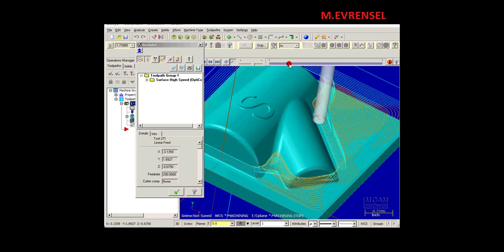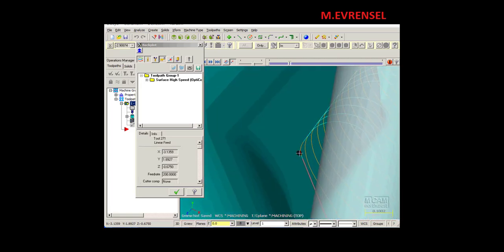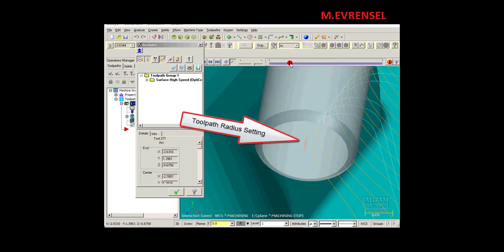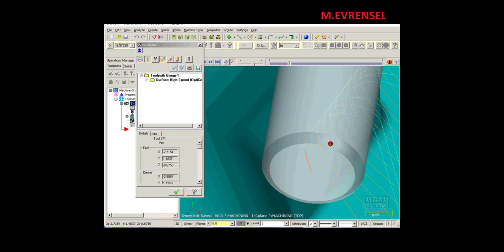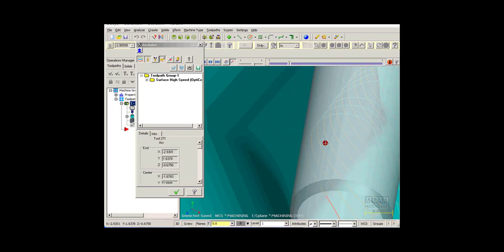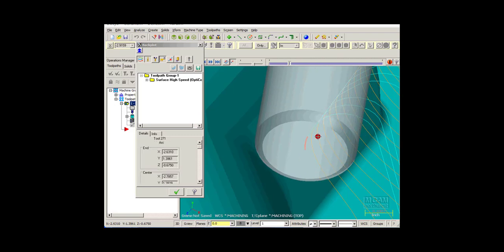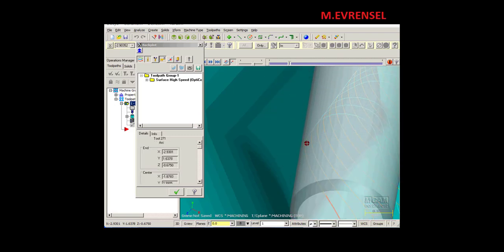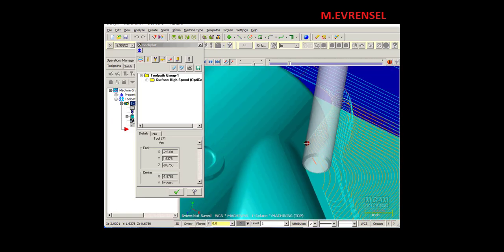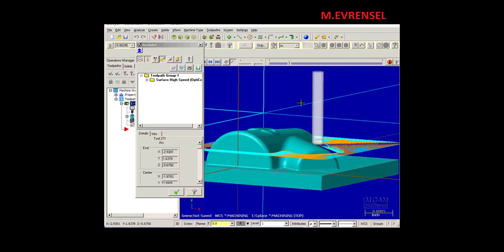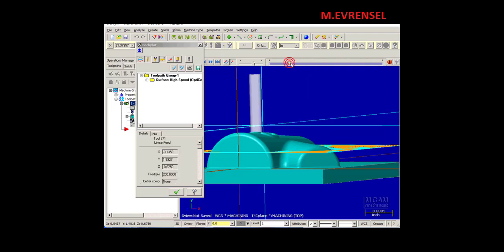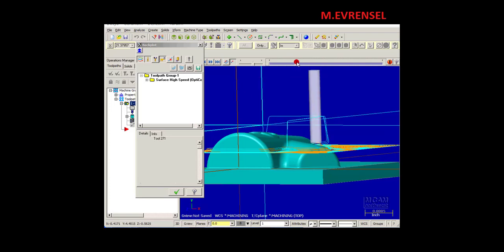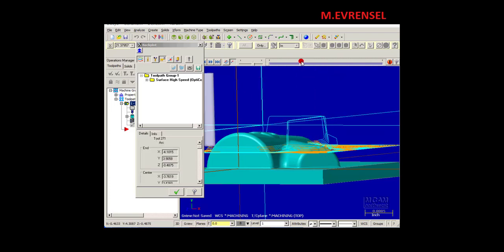Now you'll notice the detail. When the tool comes into a corner here, it's actually cutting a radius. It never will go into the corner and use the tool to form the radius, which would no doubt break at this feed rate and this depth cut. So that's the rounding radius we're seeing right there. Probably the most important feature in these high-speed toolpaths. So there's our 3/4 inch step down, and here's our step up now that we see.